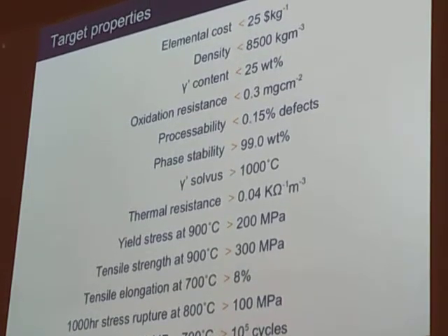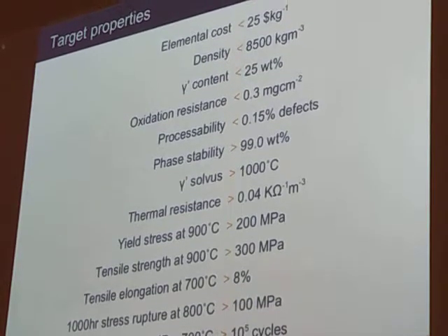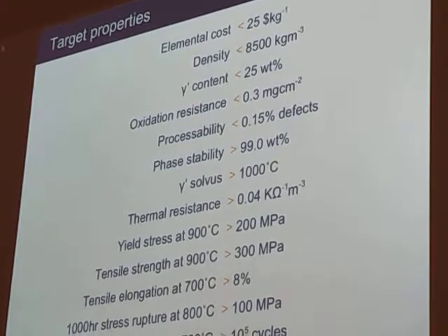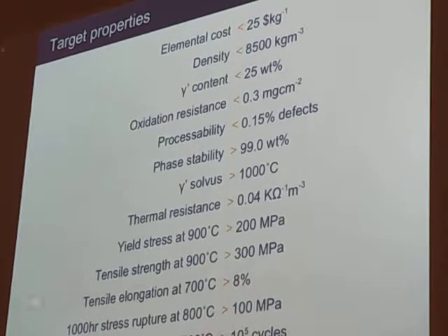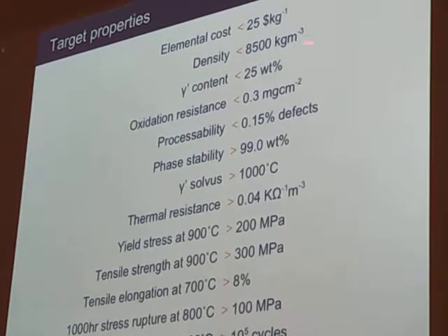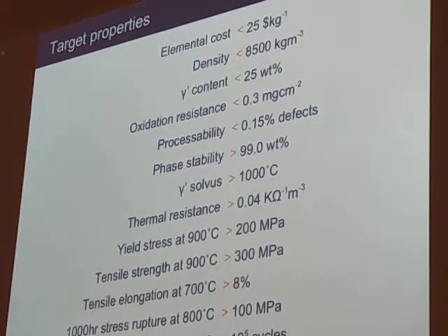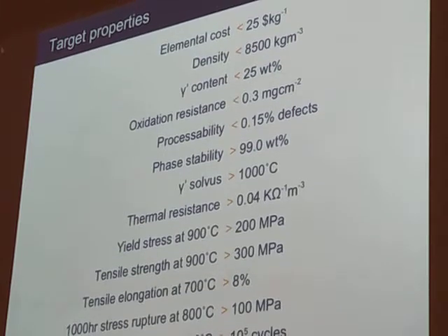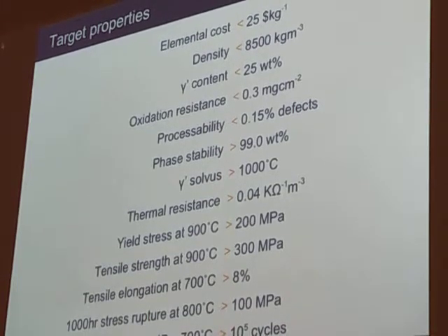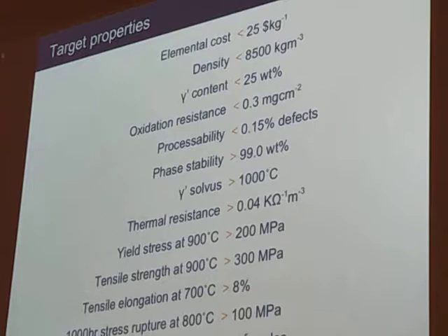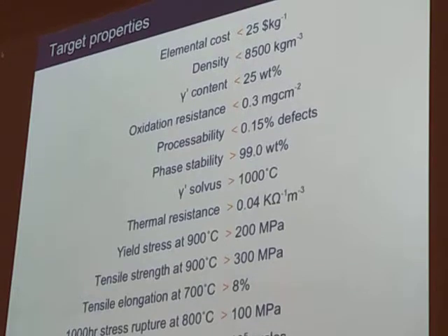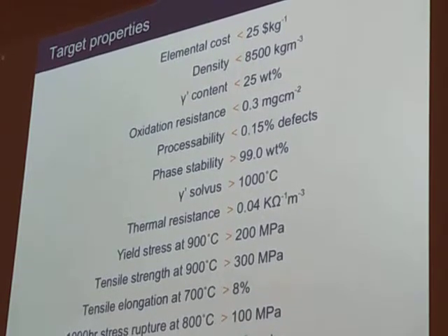So we've got here a slew of all of the physical properties we've got to get right, and to predict these we've got to go off and get models for all of them. Typically that would be from an experimental database. For some of them, like the phase behaviour, the amount of gamma prime in the sample, it's a particular phase that's formed. We know physically what we expect. That's something that we actually get using the CALPHAD method. It's a thermodynamics tool. We can bundle together all of these sources of information, though we get very different amounts of information per quantity. There are also some other hidden ones, like the weldability, that we're not setting targets on.